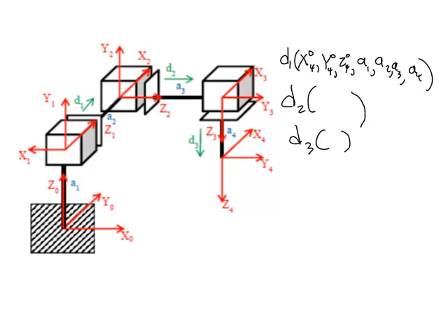If we have these equations, then we can put these equations into our robot control program to command these three joints, which we have control over because we have motors on these three joints, in order to place the end effector in whatever location X, Y, Z we want it to be in.